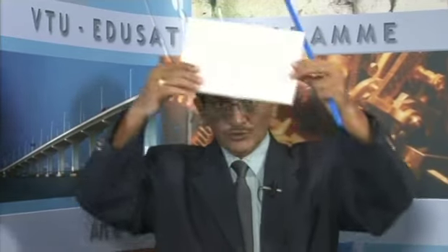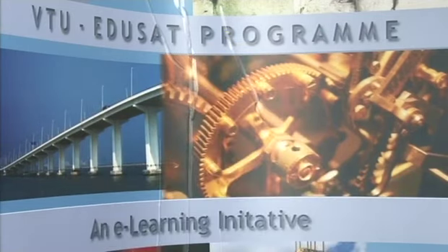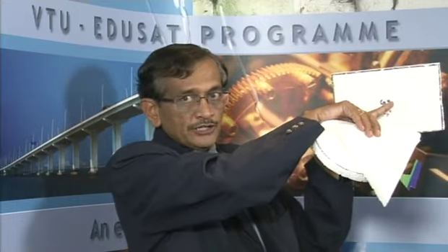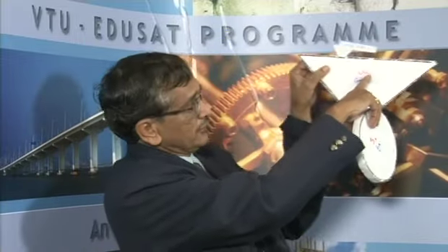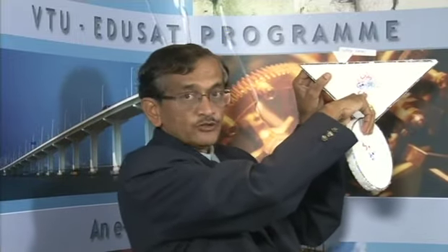So, this also gives an idea how to calculate the forces on rectangular vertically immersed, then triangular also we have done, then we have done circular also. So, that has given you an idea. We have taken the 3 problems today. One, we have gone with the rectangle, how the centroid is here, center of pressure here. We have taken next problem on the triangle, same thing, centroid was here and hydrostatic force was acting at center of pressure, which was slightly more. You remember the answer was 1 and 1.5, and circular case we have also done same thing, centroid was here and center of pressure was here.